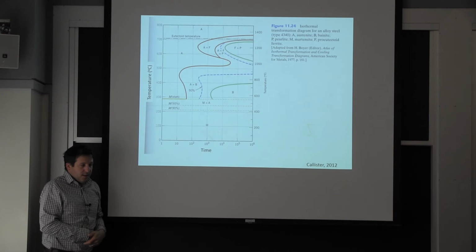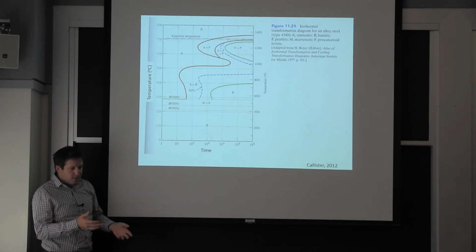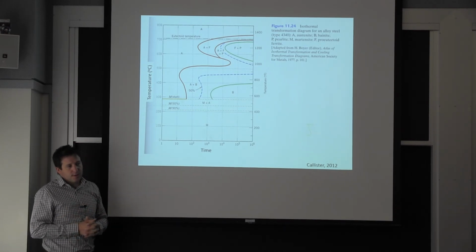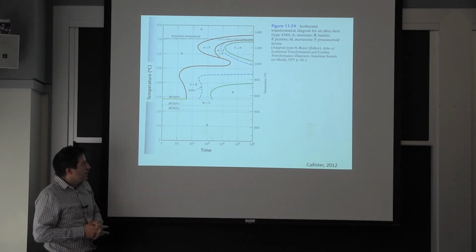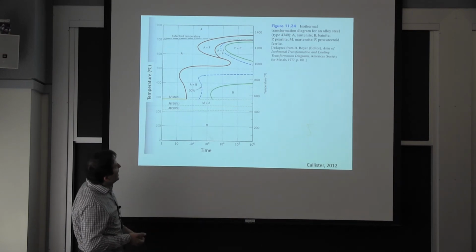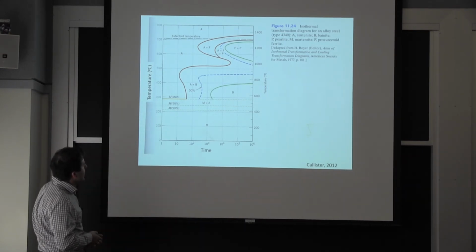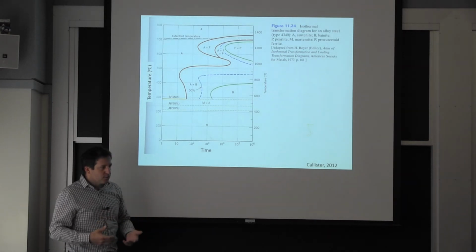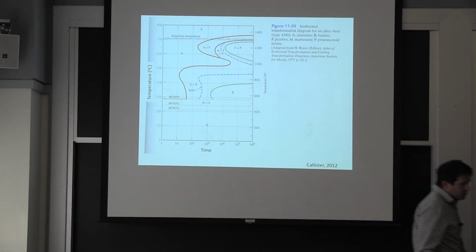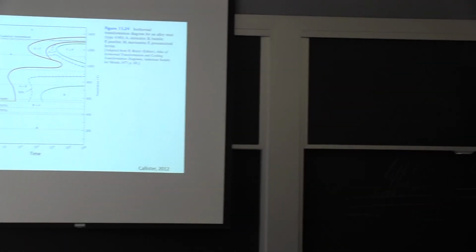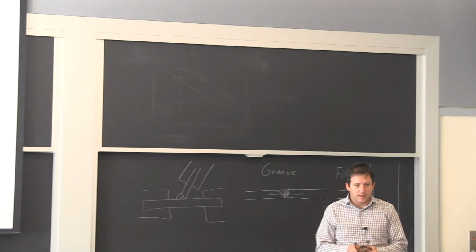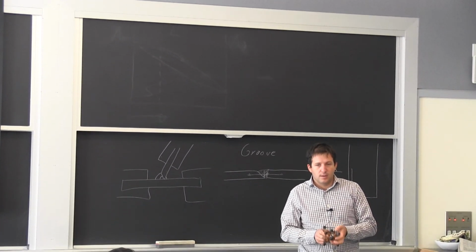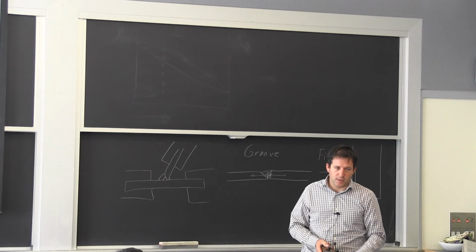That's much better than seeing all these differences that I was just showing between, oh, I cool it in the oven and I cool it in the air, see how different it is. So by adding a little bit of nickel, chrome, there are other alloying elements, what you do is you delay the transformation. These are extra solid solution pieces in the austenite that will not fit nicely in any of the other structures, and therefore it prevents the initiation of the transformation.